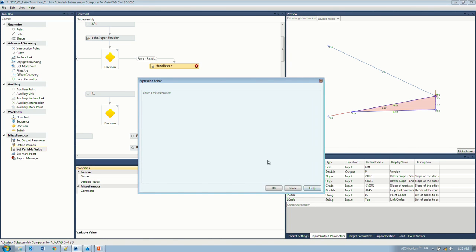So this is the magic formula as I like to call it, because when I found this, it just opened Civil 3D up to me completely. It just completely changed everything. Double open bracket. This is the subassembly API, once again, baseline being your baseline, dot station, so this is the current station value, minus baseline dot region start. I'm not expecting you to remember this. It's all in the documentation. I'm just typing it out to remember myself. Baseline dot region end minus baseline dot region start.